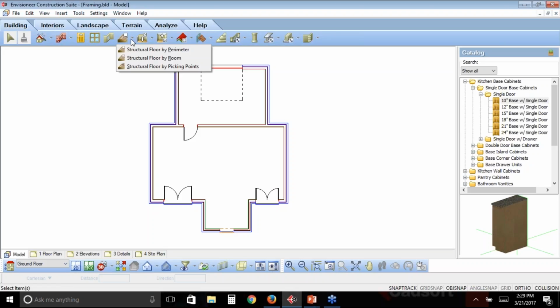This particular tool will allow you to lay out the joists, the rim joist, the band joist, the sill plate, and the subfloor all at the same time. If you're not using Building Essentials or Construction Suite, you're using our regular floor tool that has the floor joist associated to it and only a finished material on top of that. It doesn't have the comprehensiveness, but you can get floor joists from there.